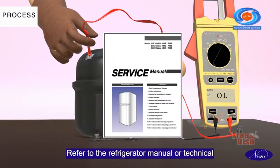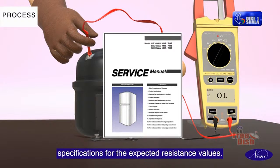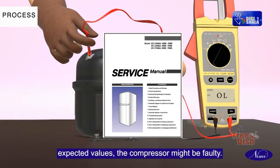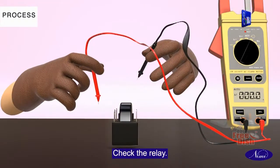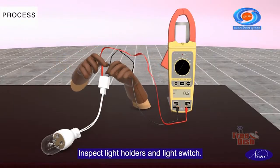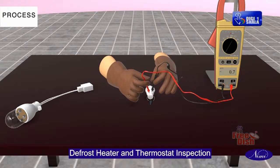Refer to the refrigerator manual or technical specifications for the expected resistance values. If the reading significantly deviates from the expected values, the compressor might be faulty. Check the relay. Inspect light holders and light switch.